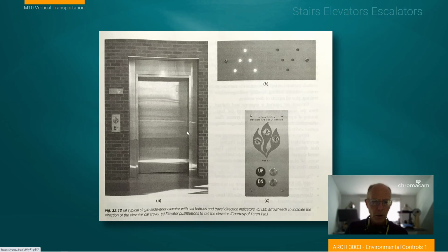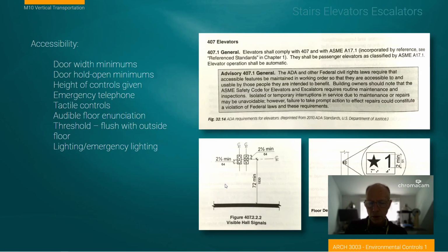Now, this is out of our textbook, really a sad visualization of elevator design being in black and white. But I put this in here to remind you that there are going to be a lot of issues about safety and informing the occupant of where the elevator is: the signal systems, how they look, what their presentation is, and how that matches with the theme and the concepts of the building. So these are all places for designers to participate in activities. Some are required to be certain ways just for code, such as labeling systems, but other times architects have opportunities to intervene and control the way certain things look.